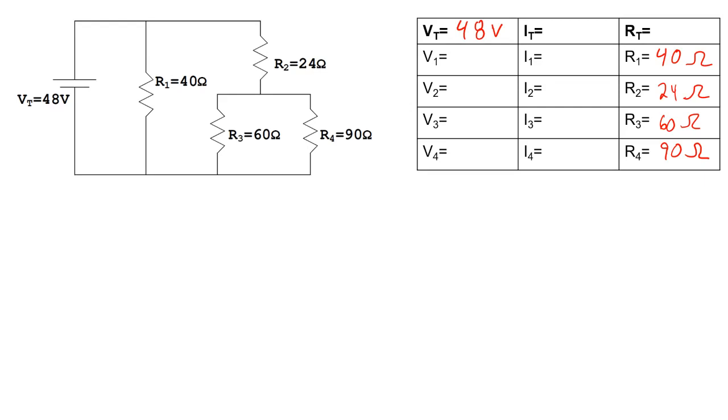Okay, so even before I go forward, we do want to find our equivalent resistance, but I'm just going to do a quick analysis and do a little thinking about this. Using Kirchhoff's voltage law specifically, I know that as I go around a loop, my voltage gain has to be equal to the voltage drop. So I'm going to look at this first loop, and again, our positive side of the battery is indicated with the long line on the battery.